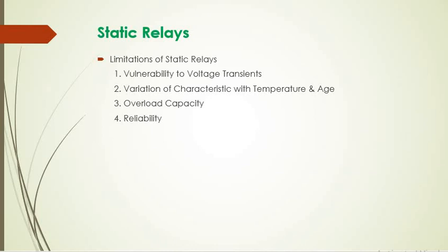Complementary MOS logic is more in use. It has the advantage of small size and extremely low power consumption. However, they have to be handled with care as they are susceptible to damage due to static voltages. ICs of digital logic circuits, operational amplifiers, registers, counters, analog to digital and digital to analog converters, and a multitude of other devices are available now commercially.